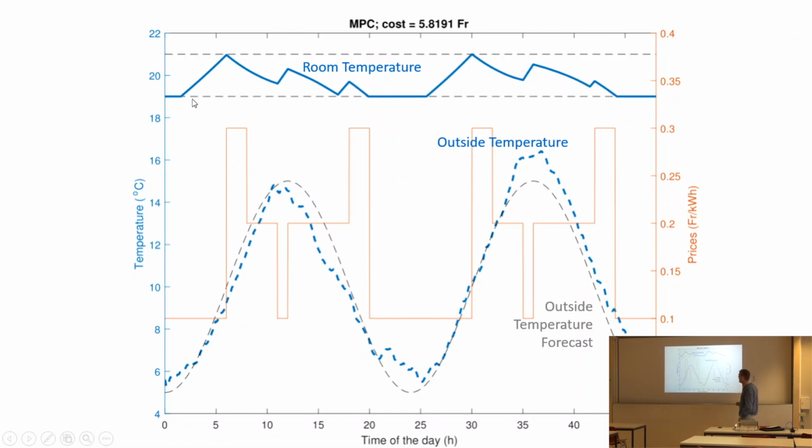The optimal solution, assuming it starts at 19 degrees here, will start heating. So here we heat the house. This is what the equations give. This gives this linear increase in temperature until we hit the maximum temperature, and then we stop heating. Since we stop heating, there's a decay, which is like a negative exponential. The house is getting cold. Those are the laws of heat. The equations of heat will give something like this here.